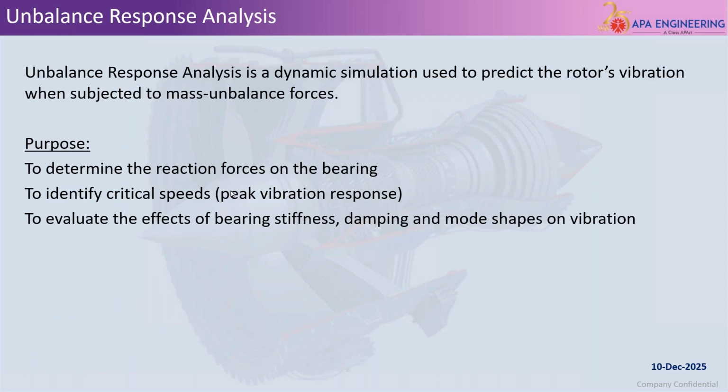We will study such aspects through unbalanced response analysis. Some of the purposes I have listed here for the unbalanced response analysis study are to determine the reaction force acting on the bearing, and to identify critical speeds, meaning the point where the rotor vibration is going to peak.